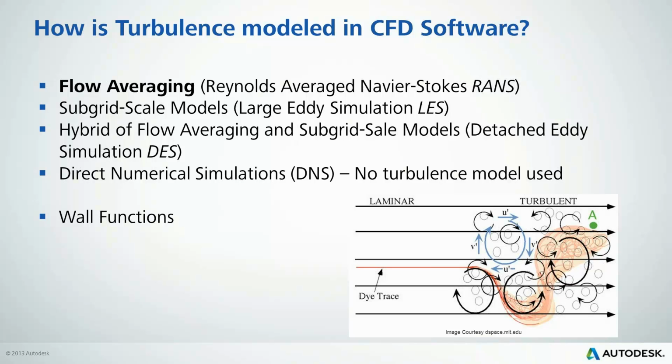From there, we get into more of a large eddy simulation. At this point, you're actually solving and visualizing those larger circular flow patterns in this picture. But the smaller eddies really are modeled within the equations. The effect of the turbulence is captured, but the flow is not really shown.